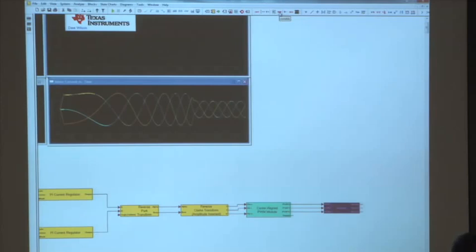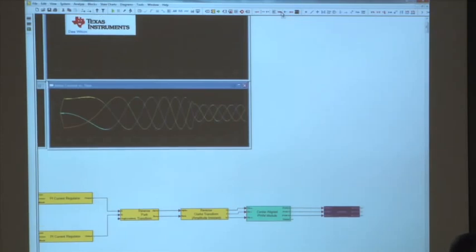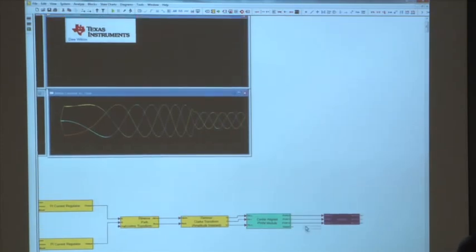It's kind of right next to that symbol that looks like a diode, but it's called VAR. Click on that, and put that on the output of, or close to the output of, the sample pin. It should drop a little block that says variable in it. Let's double click on that, and call it something creative, like sample. Change the name to sample, hit return.